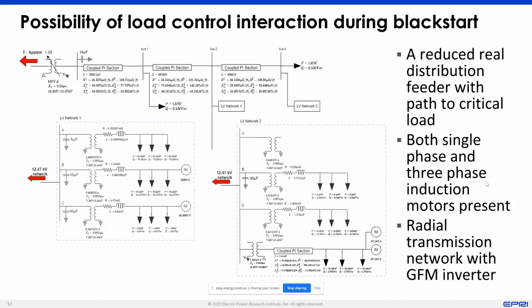All right, Deepak. On the topic of black start, we also have to start to recognize that there can be a possibility of control interactions between the type of load that you are black starting and the inverters in the system. There's one type of interaction that can come up if you're only picking up static load. There's another type of interaction that can come up if you are picking up motor load from a cold load pickup perspective, where all the motors just start up. There's another type of interaction that can come up if the motor loads have a soft start mechanism embedded in them, where the motor slowly ramps up.